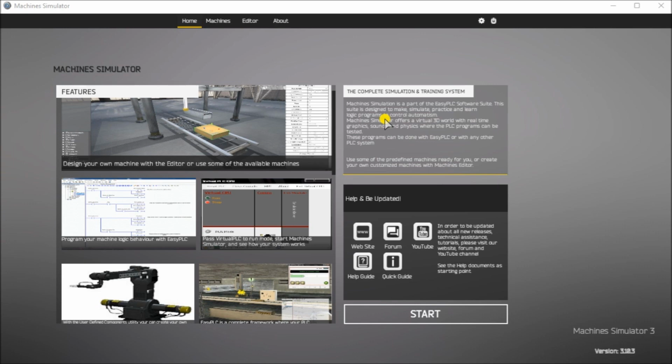This will demonstrate a sequencer example. The logic will step through different steps in order to perform the task. In this case, an engine is lifted and placed onto a rack or pallet. We will be using a Productivity Suite programming simulator to program this engine loader of the robotic cell. This will be done using Modbus TCP or Ethernet for communications. Using the 5 steps for programming development, we will show how the sequencer is programmed.